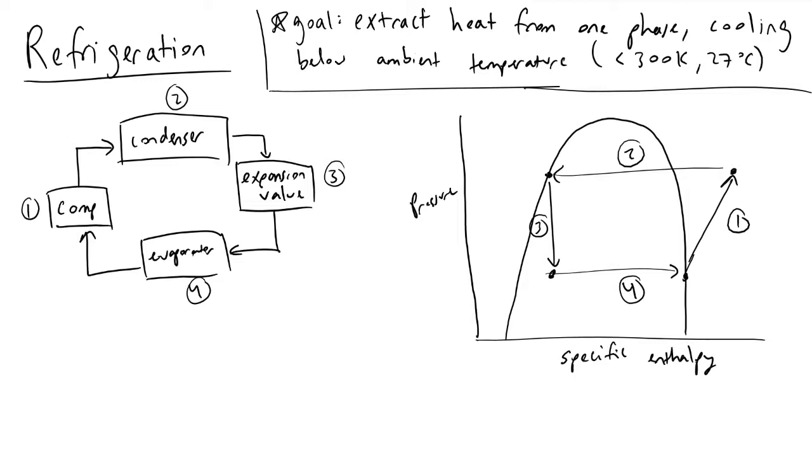And so to draw this out a bit more nicely, I have these two plots here. In the plot on the left, we see our evaporator. And so what's going on here is we are pulling heat, Q, out of our surroundings. And I will call this Q dot sub C. And this is to note that it is a rate that is occurring because your car is operating continuously. It's pulling a certain number of joules of heat out of your car per second.